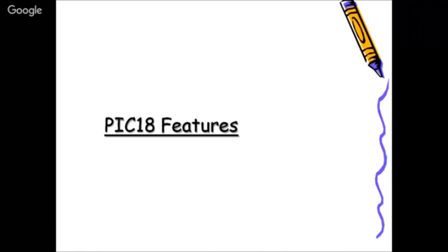Now we'll see a little bit about the specific features of PIC 18. Today our interest is only to touch upon some important basics and some understanding about the PIC family. As I was telling you, architecture wise it differs from your 8051. We'll try to contrast it with Intel's basic 8051, which most of us are familiar with. It contrasts in terms of architecture: it has RISC, Harvard and pipelining architecture, which makes it very powerful as far as performance goes. As a result, many features are also available.